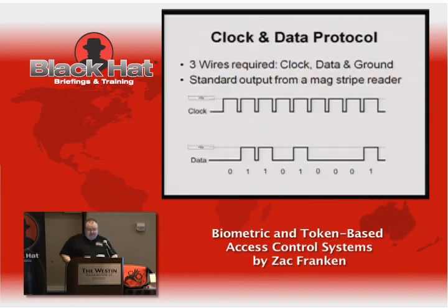Shocking, really. So generally, the classic protocol that these Magstripe readers talk is called clock and data. So here you see the clock, a regular pulse that comes out, and the clock basically specifies what the data line is doing. So on a clock pulse, it's going to look at the data line and work out whether it's actually sending a 1 or a 0.